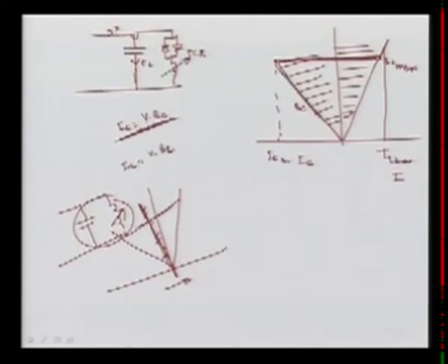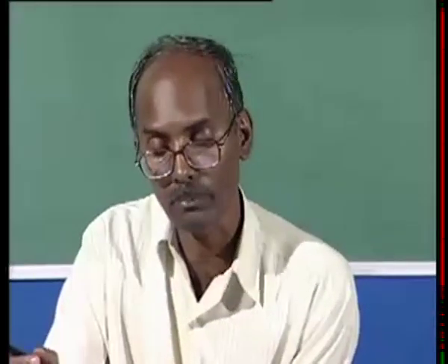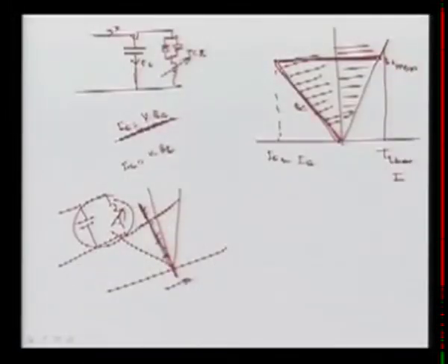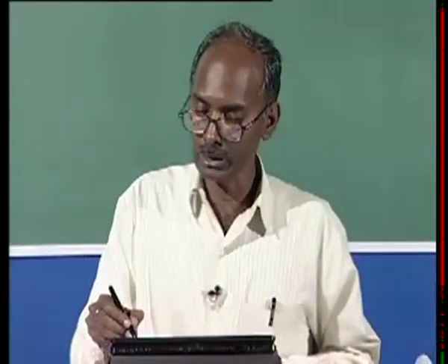We operate normally in the capacitive zone. When the voltage is less, we must operate in the capacitive zone, where we require reactive power and we must supply it. So our characteristic here normally moves here, then slightly going here, and then at this point. It means when the reference voltage value is less, we have to operate in this zone because we have to provide this. If voltage is more, then we have to go this way.